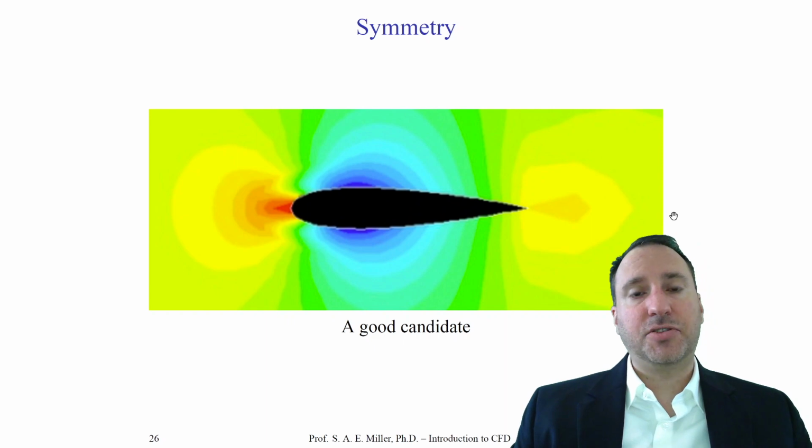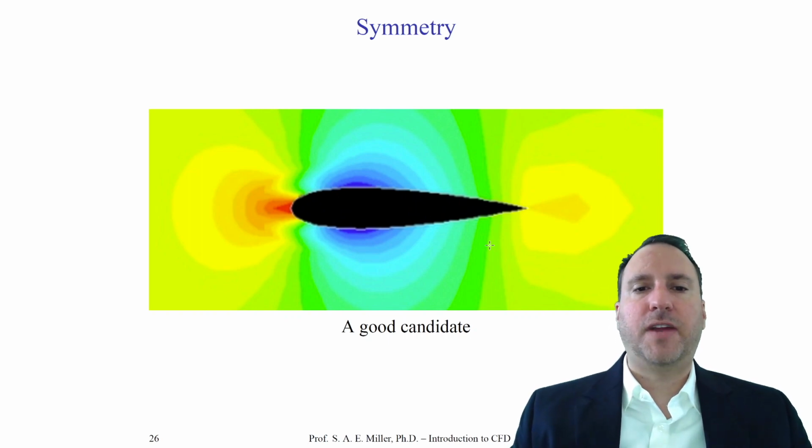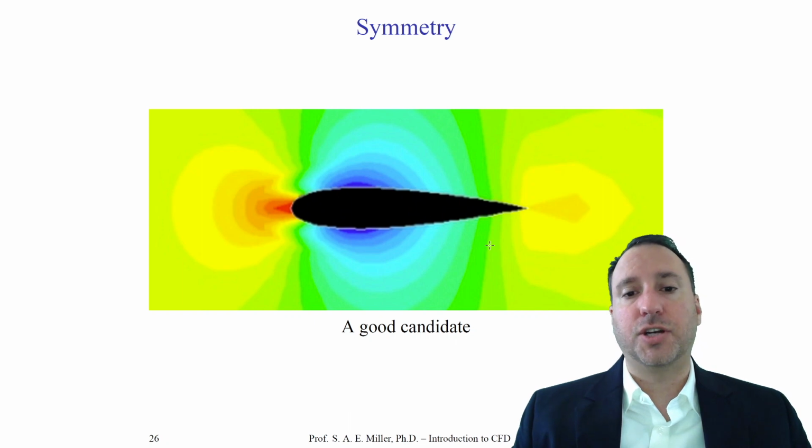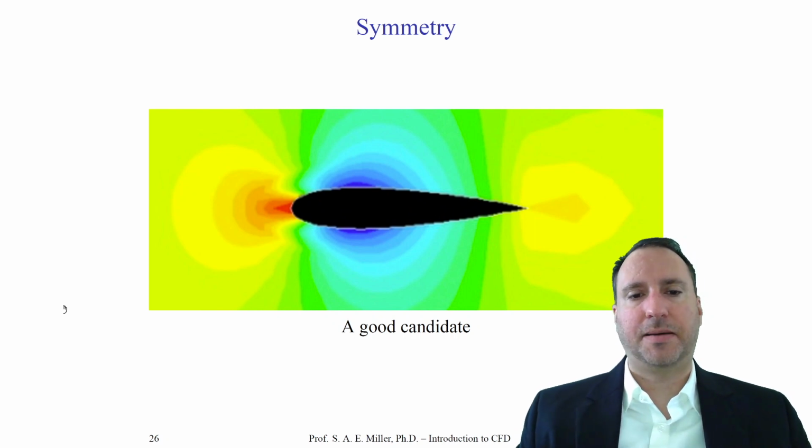I could apply a symmetry boundary condition to the simulation by simply cutting the grid through the middle and ending it at the leading edge, keeping it along the top edge, and having another cut through the back plane. So you can imagine you can put your hands over the bottom part of this page and only solve the upper part of the domain. You've cut your number of grid points in half by applying the symmetry condition, because you know in advance for a steady, statistically stationary solution that you'll have a symmetric solution. And we'll talk about this in our class and try some examples.